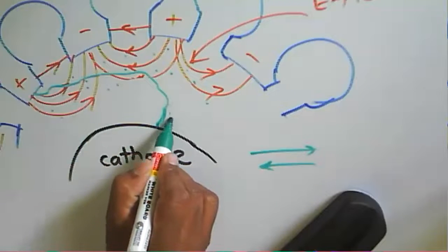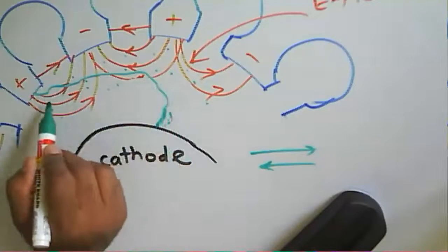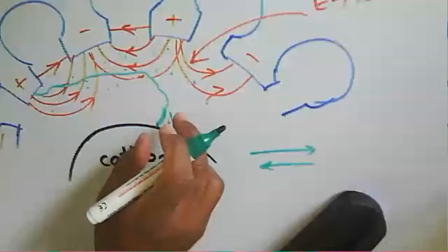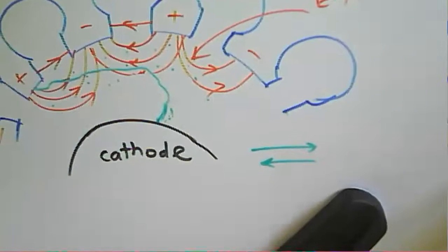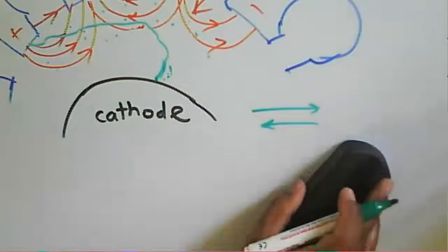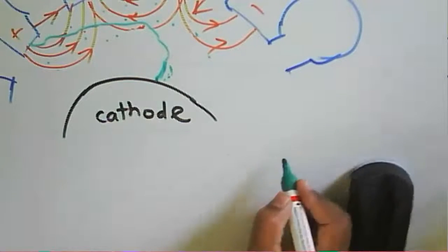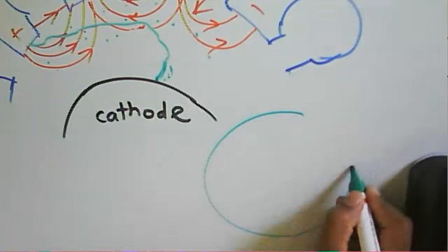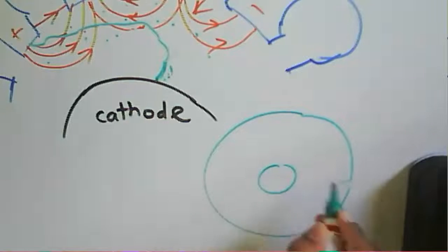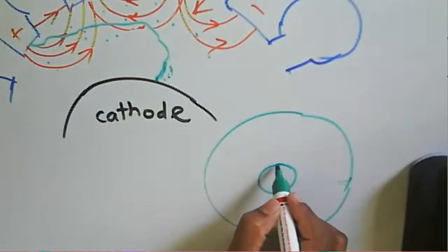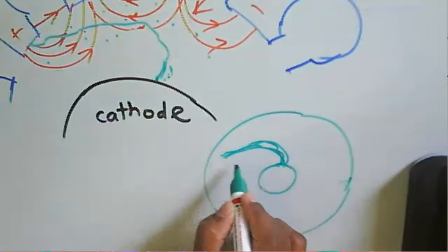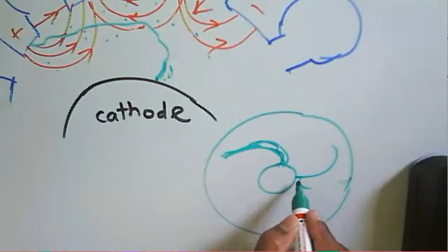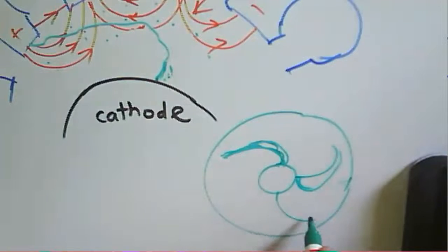It is not about a single electron. There are a large number of electrons; they will move and bend here. At the end, the electrons will terminate at this plate and give up their energy to the RF field. So how will it look when we consider this as the cathode? Electrons will move along this particular path, many electrons, and it will look like spokes.